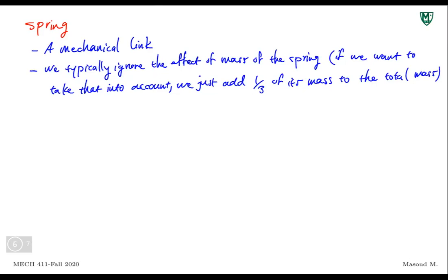And in a spring, again, just a review, the force is related to the deflection of the spring. So the further we deflect this spring, the more force it applies. This is a tension spring, but if it's a type of spring that you can push and pull, even if you push and compress it, it's going to apply a force. So there's always a relationship between force and deflection. How are they related? Well, the way they are related tells us what kind of spring we're dealing with.